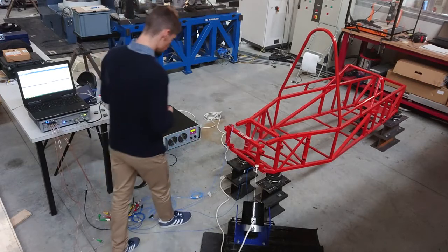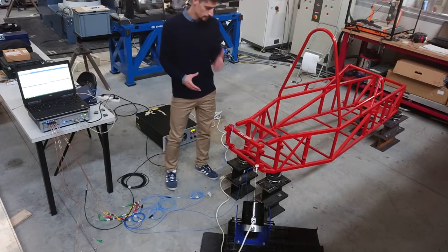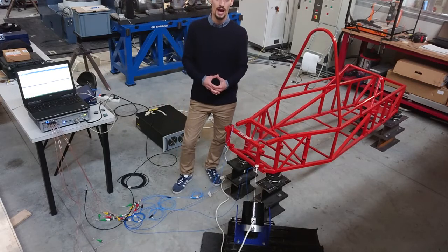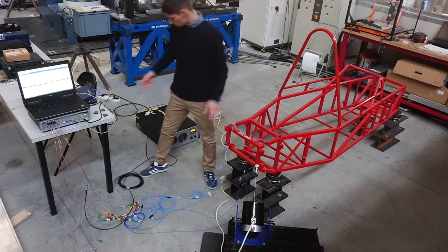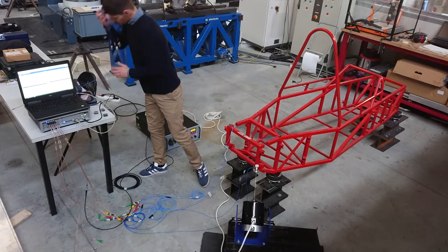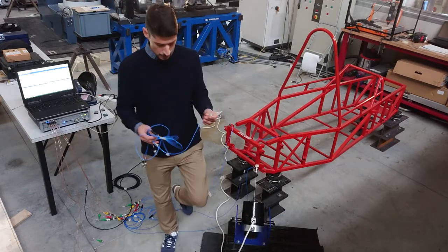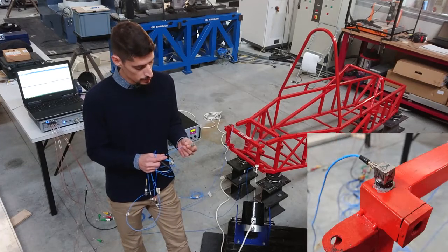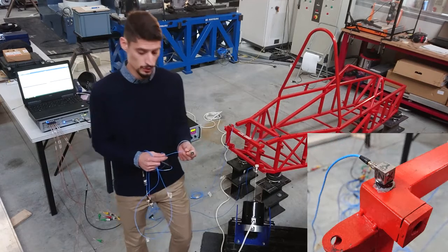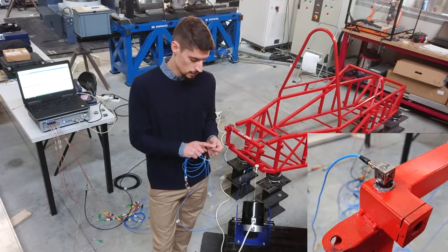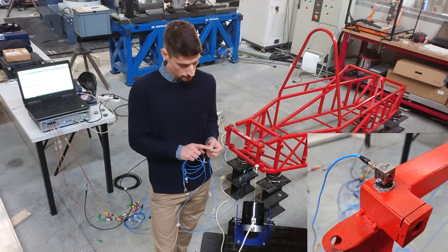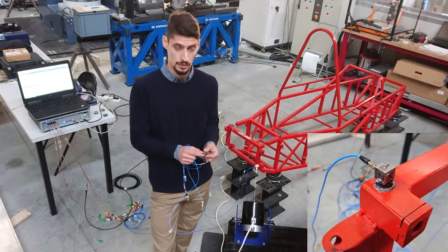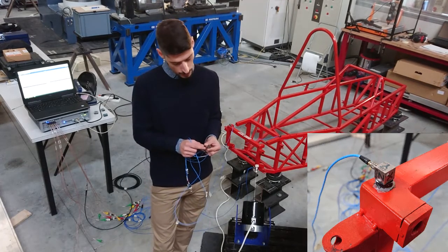At this point, we need some sensors that can measure the dynamics of our structure, and to do that we will use a set of 3 axial accelerometers. This is a 3 axial accelerometer, you can see. Of course, a 3 axial accelerometer can measure the accelerations along 3 directions simultaneously. And as you can see on top of the faces of the accelerometer, there are some markers, X, Y, and Z, that tell you along which direction the acceleration is measured, and give you the local coordinate